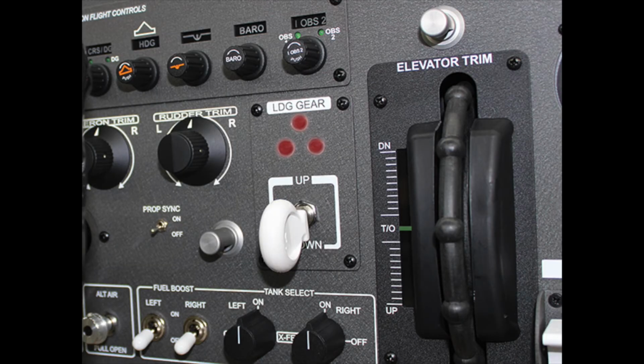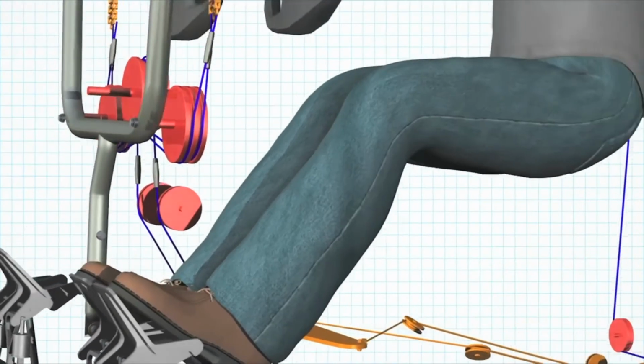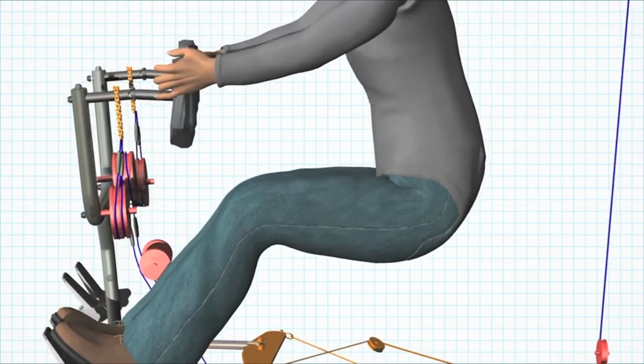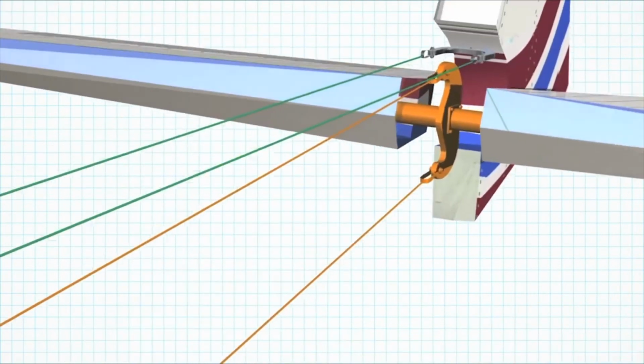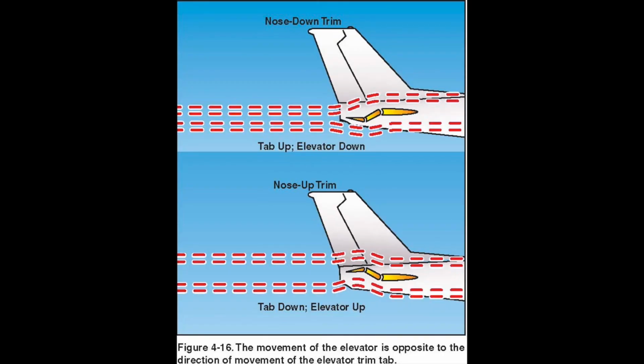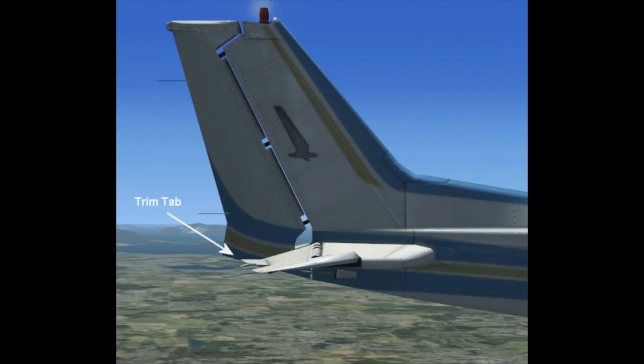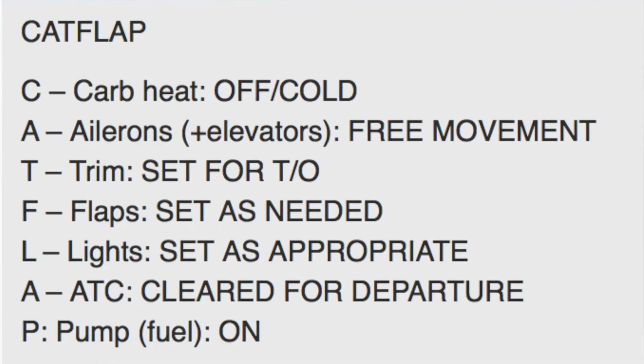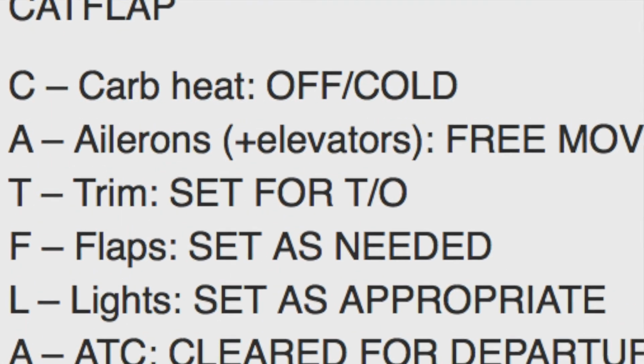For instance, if a pilot wants to descend, the control column is moved forward, directing the elevator to move downwards. If the pilot is using trim, the trim tab will move upwards on the elevator, and doing so will apply a force to cause the elevator to move downwards. The airflow across the elevator will be directed downwards, thus raising the rear of the aircraft, and so begins the descent. Trim is set when an aircraft is out of balance, such as to counter a tendency to turn, climb or descend. Before takeoff, setting trim is part of the pre-takeoff checklist.